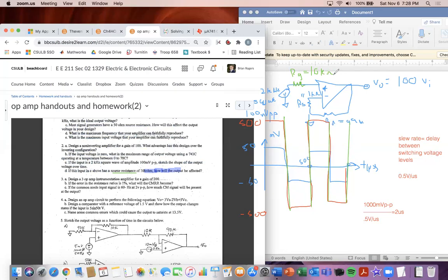So this output voltage, if you guys want to think about it, remembering his DC errors, how I told you guys the 3 equations you need to know for any possible errors when you're doing this: the output is going to be equal to just the normal. So this is a non-inverting amp. So 1 plus RF divided by RS times the input voltage, plus the next one, which is going to be offset voltage.